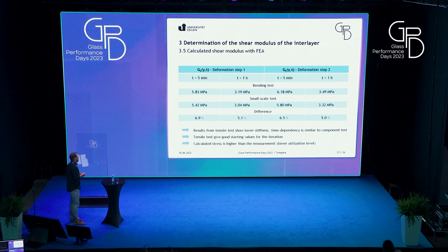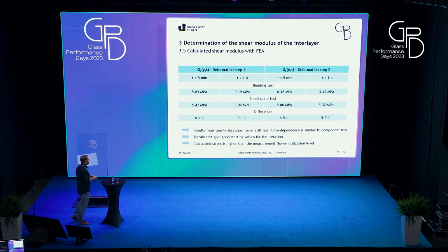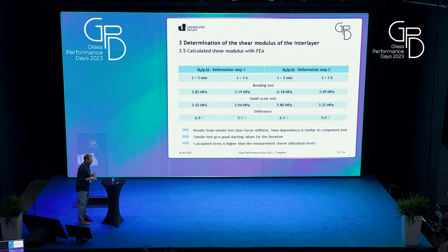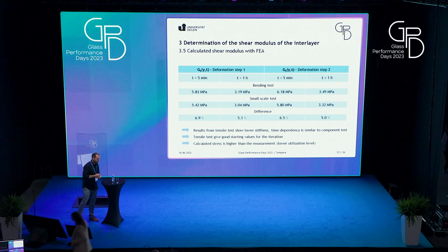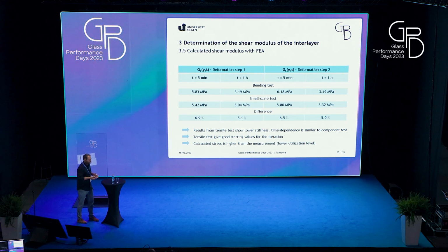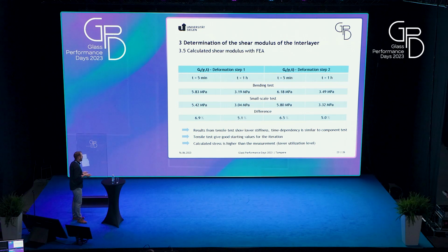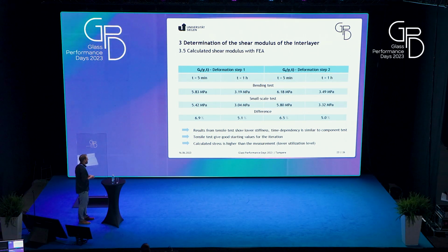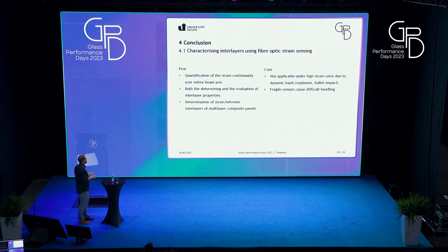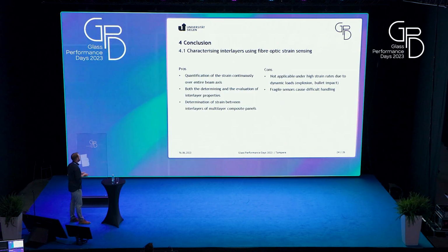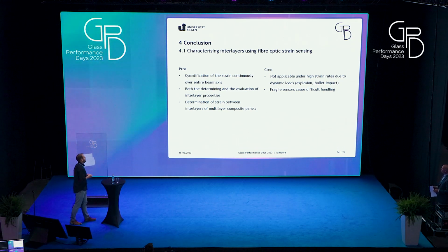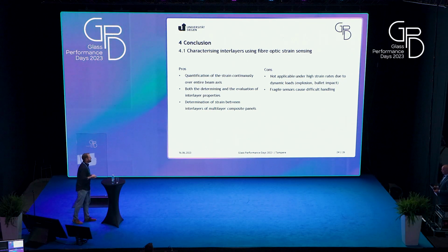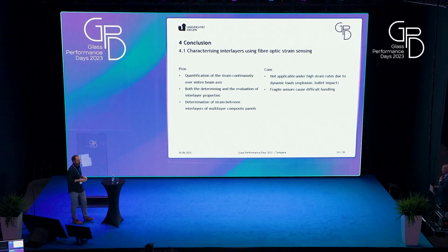Okay. The results from the tensile test show a lower stiffness. So if you determine values from the component scale, it is, in my opinion, possible to define constructions in a better way. And the calculated stress is a little higher than the measurement. Okay. The pros are that the quantification of the strain is possible. The cons, it is not applicable under high strain rates due to dynamic loads, and the sensors are very fragile.